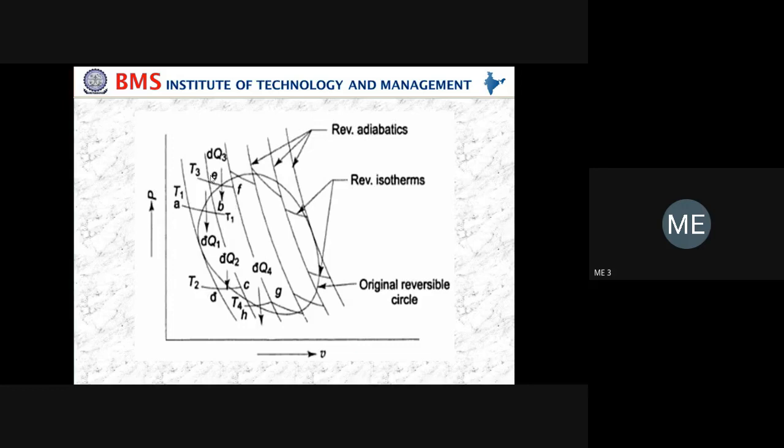In between, you draw two or three adiabatic lines. You have to cut at the top and bottom by isothermal lines. Okay, so this is how to draw the PV diagram for Clausius theorem. Once you draw this, you have to represent it. Here it is T1. An isothermal line means the temperature remains the same, T1, and here also the temperature remains the same.